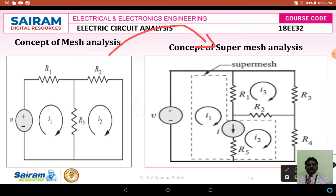First of all, let me ask the question: why do we have to apply supermesh analysis? Why approach the supermesh analysis technique instead of mesh analysis? Because in the circuit where we applied mesh analysis, there is no current source between the boundaries of the two loops. For that case, it is easy to apply mesh analysis. But if there is a current source between two loops or two meshes, at the boundaries of the two loops.